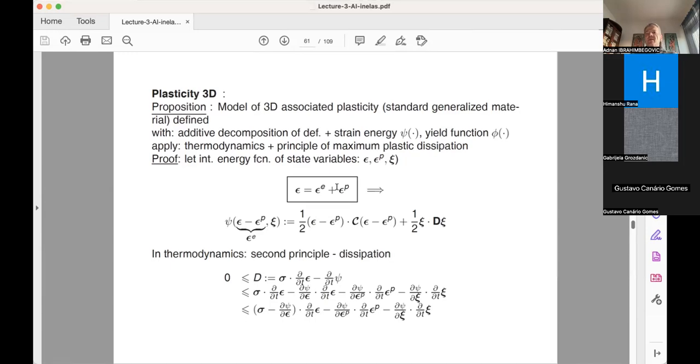Now, for different materials, not all strains will be triggered, but this way we have generality to treat the most general setting that you can possibly imagine. So the second ingredient is to provide the potential. If you quickly copy the case of the one-dimensional problem, the only thing is we are now using boldface letters to describe the strain with the 3x3 components.